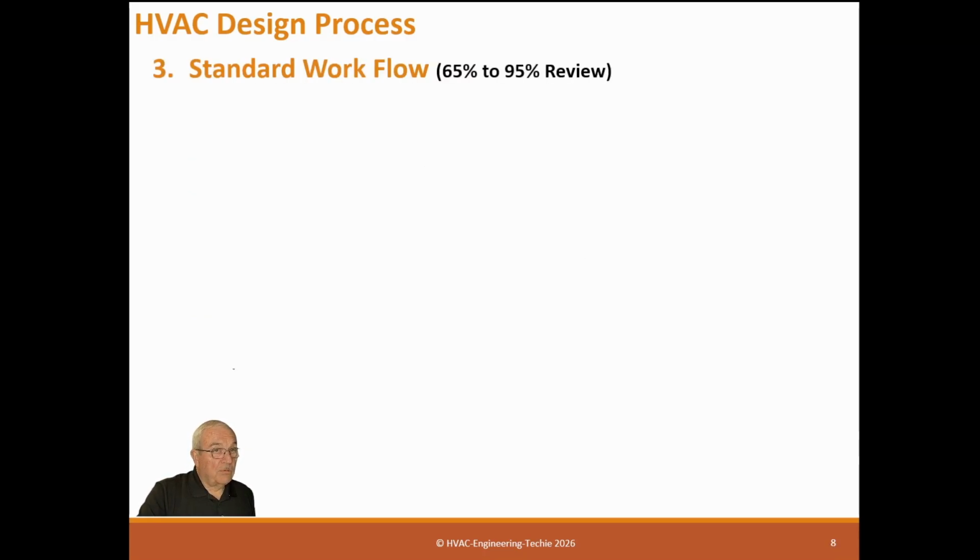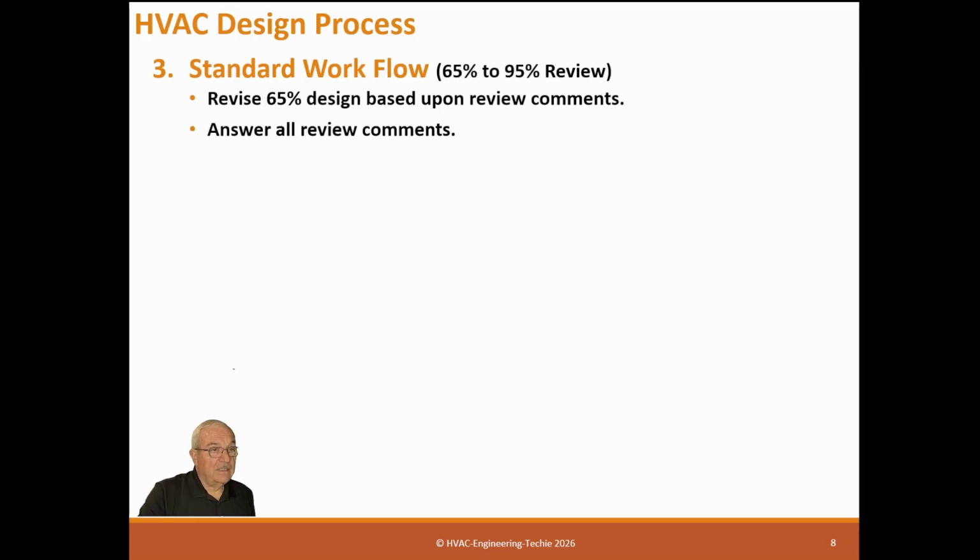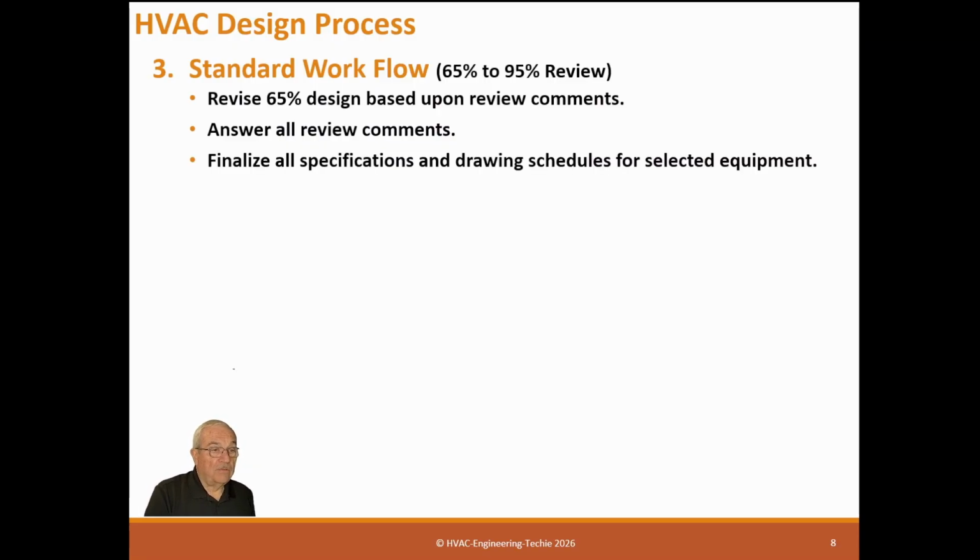Now, what's the standard workflow from 65 to 95? This one's not too tough, actually. It revises 65% design based upon review comments. Again, 65% was the big review, so you should get the most of the comments coming back at 65%. Need to answer all comments, all of them. Even if it's the ones you don't like, you still have to answer them.